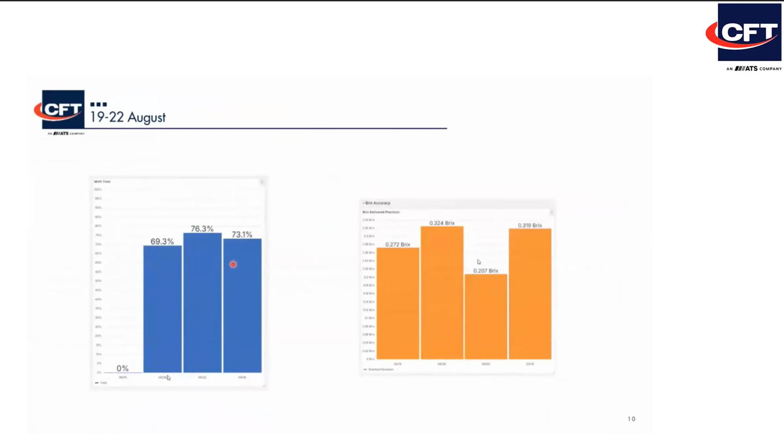Finally, these final charts show how a human intervention of the operators, by changing slightly some of the algorithms in the final part of the season, had a huge impact on productivity and energy saving. For instance, the MVR yield rose from 69 to 76% due to the modification on the controlling algorithms.